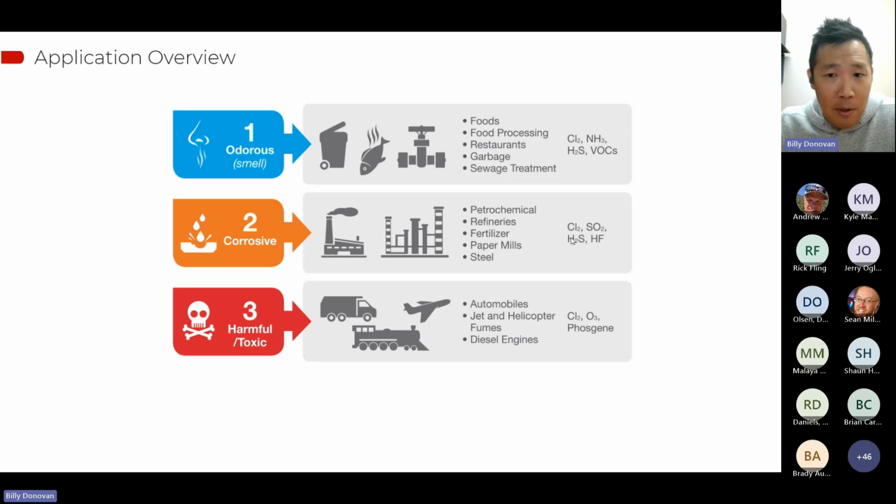Some examples are, hospital helipads and airport terminals are generally challenged with Jet A fumes entering their outdoor air intakes. IVF clinics are concerned about VOCs that are just in the outside air because of pollution. VOCs have been shown to diminish their success rate at IVF clinics.